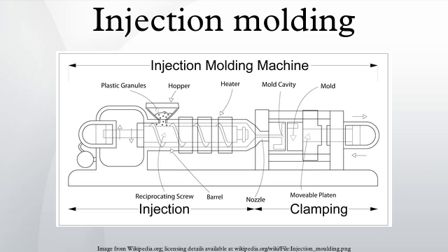For thermosets, typically 2 different chemical components are injected into the barrel. These components immediately begin irreversible chemical reactions which eventually cross-link the material into a single connected network of molecules. As the chemical reaction occurs, the 2 fluid components permanently transform into a viscoelastic solid. Solidification in the injection barrel and screw can be problematic and have financial repercussions. Therefore, minimizing the thermoset curing within the barrel is vital.